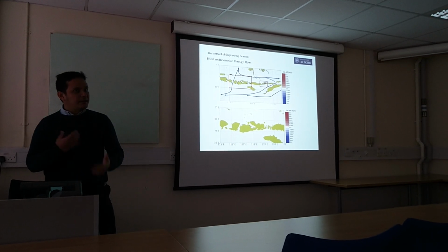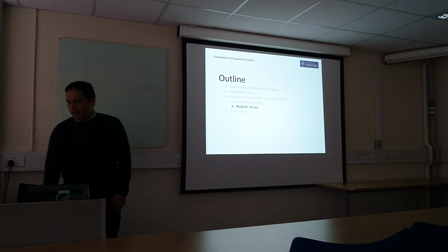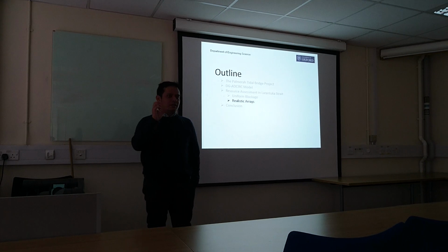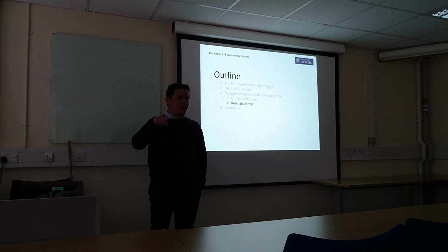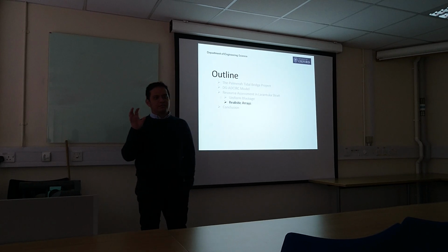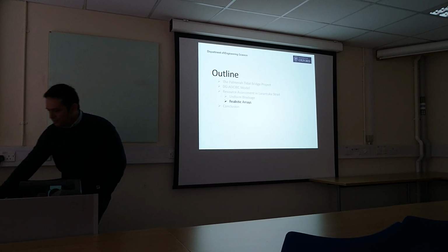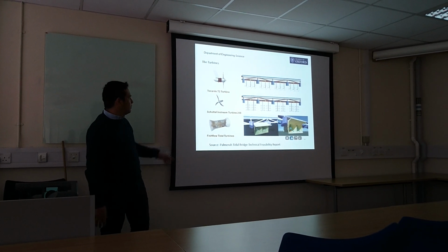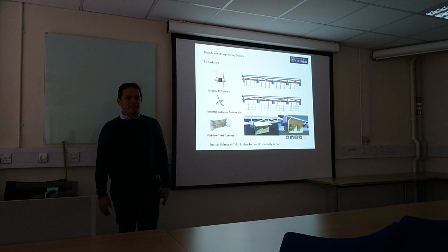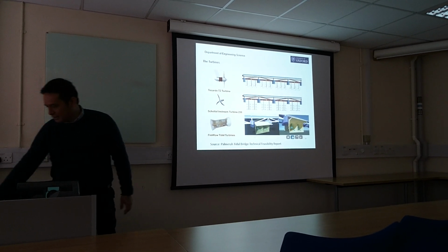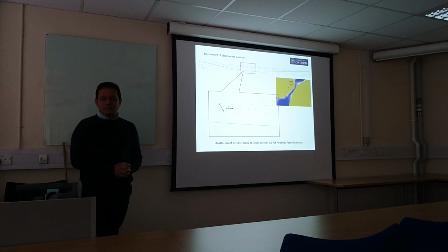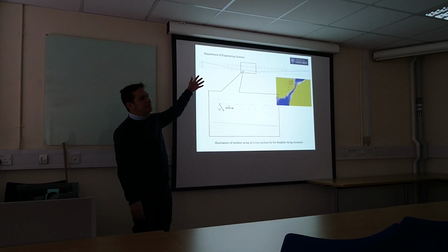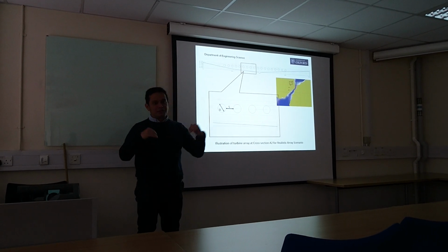Okay, this is the other thing that we have to consider. Since the previous one used a uniform blockage ratio, which is not realistic, because in each element you have a different turbine size, in this case I try to follow this turbine. This is actually from another article, but you can find this turbine specification online. So this is the illustration, even though it's quite simplifying the shape of the cross section of the arrays like this.